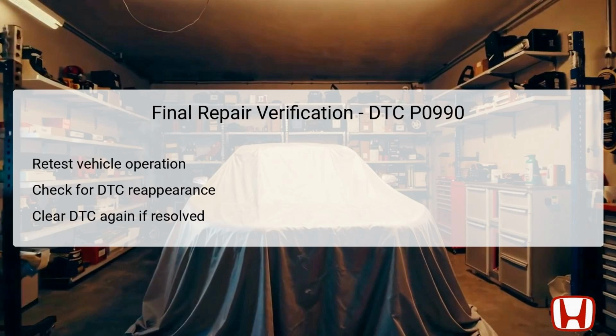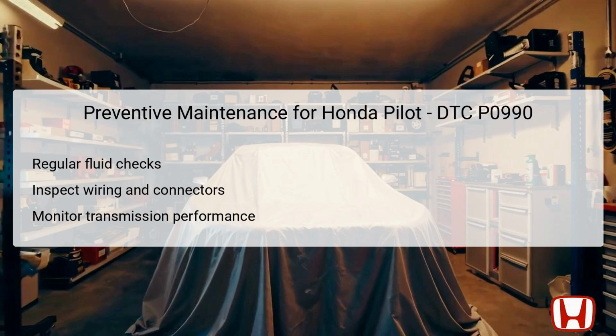If the code does not return, this is a strong indicator that the repair was successful and the issue has been resolved. For final confirmation, clear the DTC again using the HDS and perform a test drive to monitor the vehicle's performance under various conditions. This complete verification process not only builds confidence in the repair, but also supports maintaining the integrity and reliability of the transmission system. Preventive maintenance plays a vital role in avoiding issues such as DTC P0990 in the Honda Pilot.